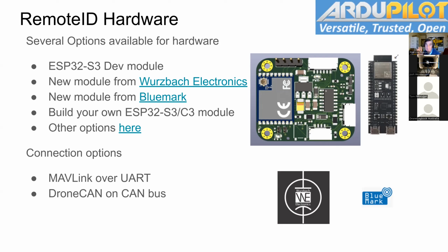Just be careful about FCC requirements and the range requirements. You have to get good range out of this. The board antenna that I have on this one, that little antenna up the end there, almost certainly won't cut it. You're going to need something a bit better. Again, for RF questions, that sort of thing, talk to Jeff, or you might well be able to use the Blue Mark solution.